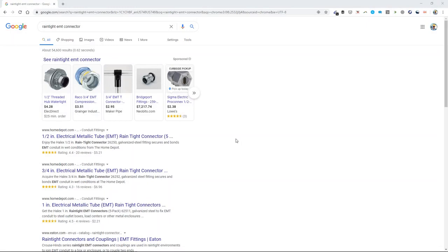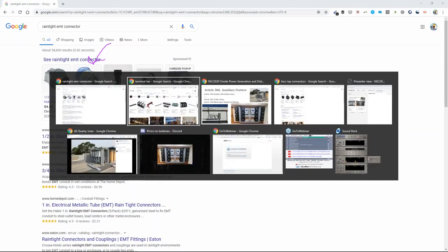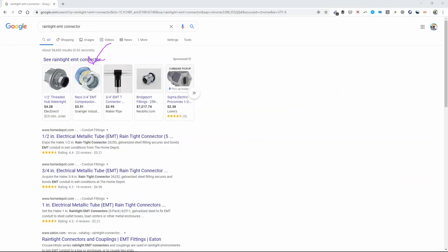Most other outdoor electrical products are either really low end and are AC and not shrouded in metal, like an air conditioning circuit, or they're high-end commercial industrial projects using rigid instead of EMT, and rigid's already rain tight. So you can't find these rain tight EMT connectors at your box stores, and often they're a special order item at your supply house. So that, I think, is a common kind of error.